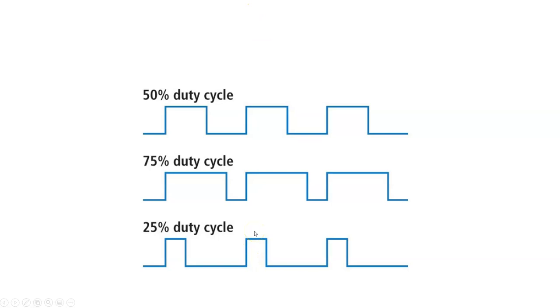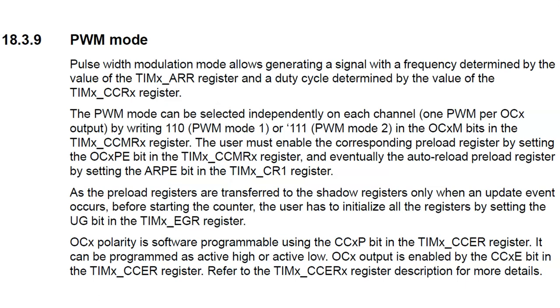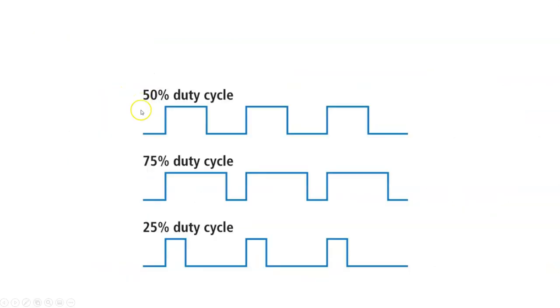So that is set by setting a value on the ARR register. That's what it's saying. And a duty cycle is determined by the value of the capture compare register settings. So if I wanted a 50% duty cycle, in the output compare, remember we said as long as the CCR4 value is less than ARR, and we set the thing to a toggle mode, we would get equal high and equal low time.